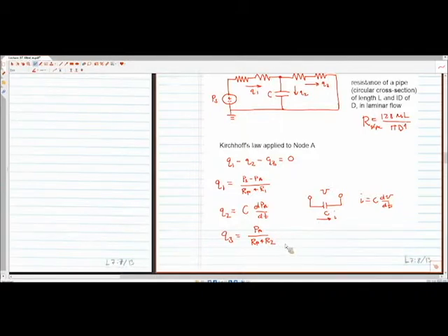Yes? We have a function for the voltage of the capacitor. Because I think we would need that if we were doing KVL, right? So your question is, if you wanted to look at this from the voltage law, how would you write the voltage drop across the capacitor? We would just rearrange this equation, so V is equal to 1 over C integral of I, basically integrating both sides to get V on the right-hand side.